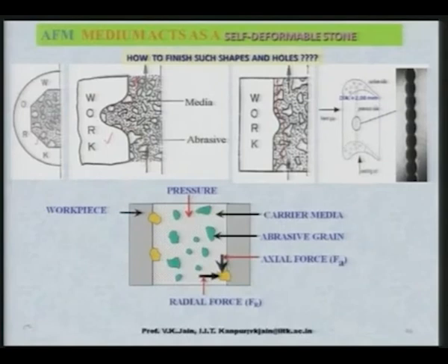Now, in all these cases the working principle remains the same. As you can see here, here is the abrasive particle which is being pushed forward in this particular direction, and at that time two forces are acting. One is the normal force, which is responsible for penetration of this abrasive particle into the workpiece, and there is the axial force, which is moving this abrasive particle either in this direction or in this direction. Then this abrasive particle will remove the material in the form of a microchip.